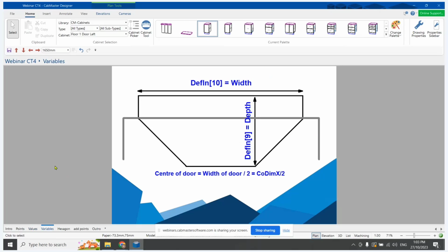We're going to start with setting out our variables. I want to be able to change the height of our cutout and the width of the cutout. We also want the cutout to be centered on the top edge of our doors. As it's an enclosed shape, to ensure that there's no unwanted radii in the top edge, the cutout will extend past the top edge of the door by half a millimeter more than the tool diameter. So if the tool diameter is 10 mil, we'll extend it past, say, 10.5, 10.2, something like that.